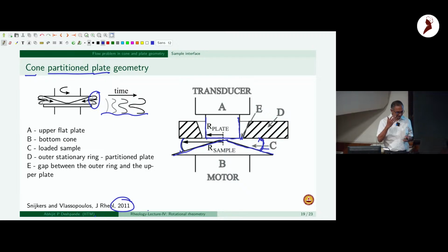But you are right that if larger particles are there, then one always has to worry about how much the edge influences. In fact, in the propellant system that I showed in the morning, the inertial effects start playing a role at 1 per second and 0.5 per second. So only at exceedingly low shear rates can one make a viscometric one-dimensional flow in that kind of material system.